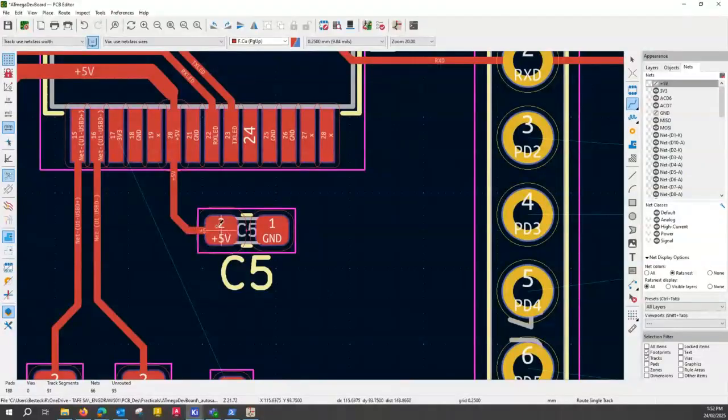The solder, while you're soldering, if you have track coming on the side, and especially if you have a skewed situation where one track comes on this side, the other track comes on the other side, those 2 tracks will pull solder in a little bit, and they might actually skew the component. So it's not a huge issue. You can still solder it in most cases.